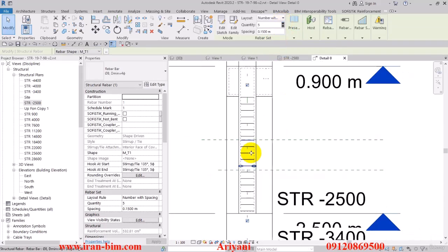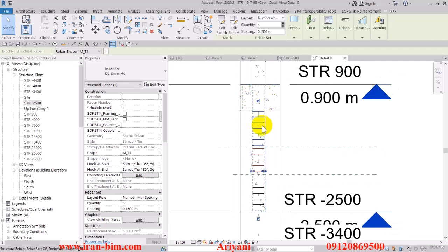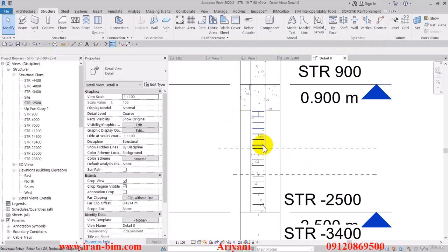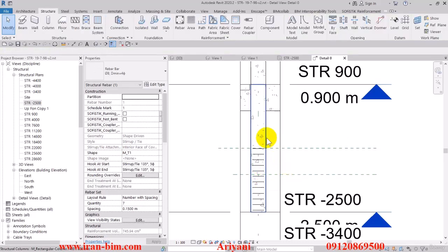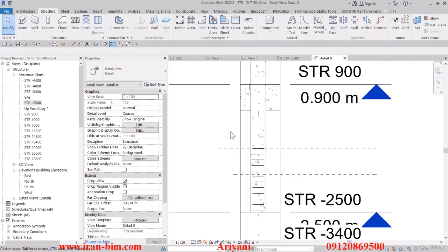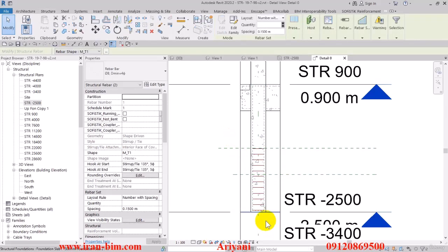Let's go with 5. So this technique that I just used is when we want to work this using the Revit file itself. Because after you've done placing the rebars, you can't really differentiate or edit them. So we'll have to do them separately. And here we could have put the same 15 centimeters of distance for all of it. But sometimes the dimensions don't exactly match up. For example, 1 meter could actually be 1.1.